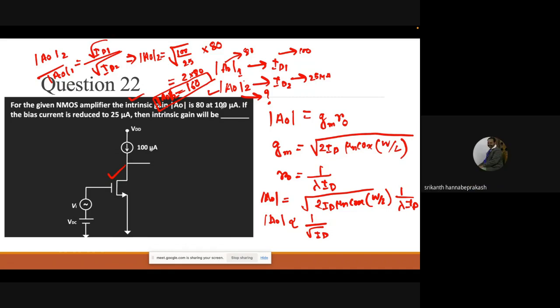This circuit cannot be said to be efficient for a particular application unless we use it. Of course, if there are high impedances which have to be driven, like a speaker or some kind of high resistance device, or maybe something not related to microelectronics, like a microscope or AFM, atomic force microscope, then we can obviously go for common drain circuits, and that too implemented with the one that is not the voltage divider.